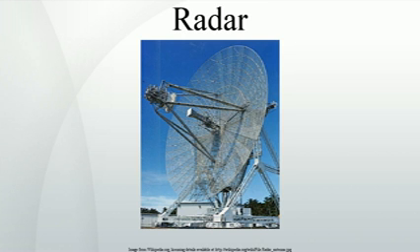The noise floor and signal-to-noise ratio are two different measures of performance that impact range performance. Reflectors that are too far away produce too little signal to exceed the noise floor and cannot be detected. Detection requires a signal that exceeds the noise floor by at least the signal-to-noise ratio. Noise typically appears as random variations superimposed on the desired echo signal received in the radar receiver. The lower the power of the desired signal, the more difficult it is to discern it from the noise.